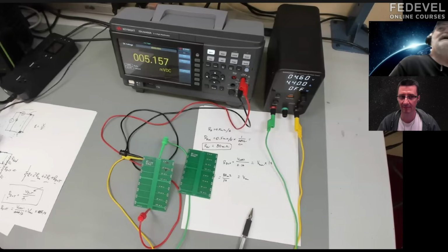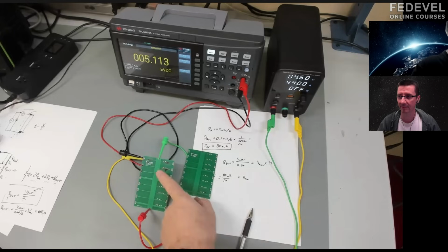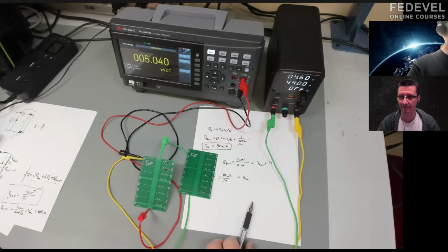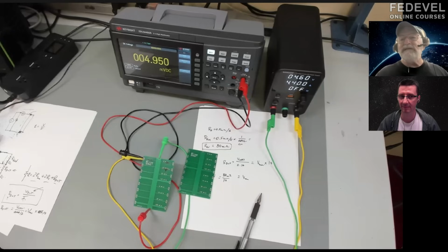We didn't do that test, but on the board I've got 20 mil, 100 mil, and 10 mil wide lines. You can put about 10 amps through the 20 mil wide line before you get thermal runaway. And the IPC spec says 3 amps as kind of the max.